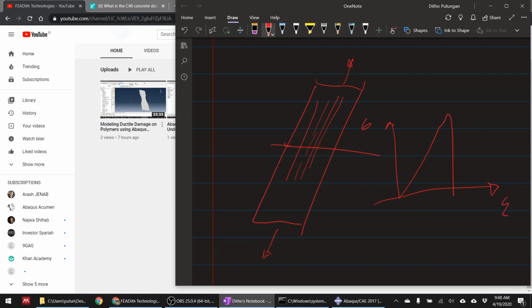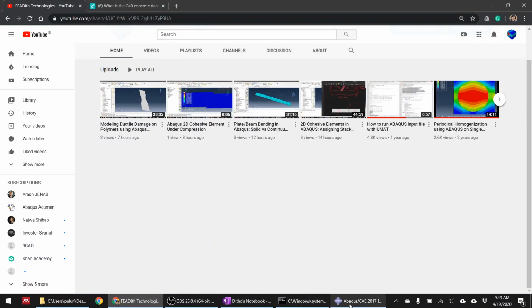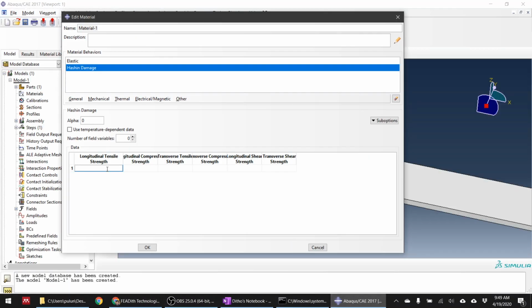So this is the kind of modeling. What you need to define is the maximum stress, sigma max, and then the energy below it, which is called the energy in the longitudinal direction. In this case, the sigma max that is suitable for this GFPP, I'm assuming GFPP now, GFPP means glass fiber polypropylene, the value is somewhere around 700 in the longitudinal direction.